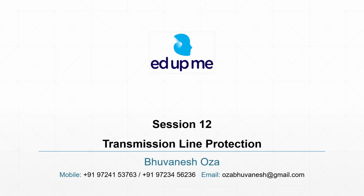You see, in this case, it is also difficult because there may be certain faults for which the primary relay may not operate and the secondary relay may not operate. Some third relay may operate, and that is known as sympathy trip. That becomes very difficult. Sympathy trip means wrong operations will be there, cascaded tripping can also occur. Therefore, researchers are trying to reduce the sympathy trip, but yet sympathy trip has not been removed as on date.